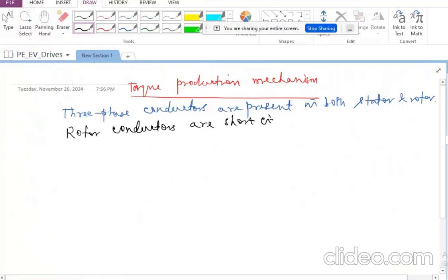And there is basically an air gap between the stator conductor and rotor conductor. That is going to cause whatever flux is created by the stator to not be completely linking, or not completely utilized to induce an EMF in the rotor. So some of it is going to be wasted because it has to pass through an air gap. The quantity of flux that is wasted, which does not link with both the stator and rotor conductors, is known as leakage.